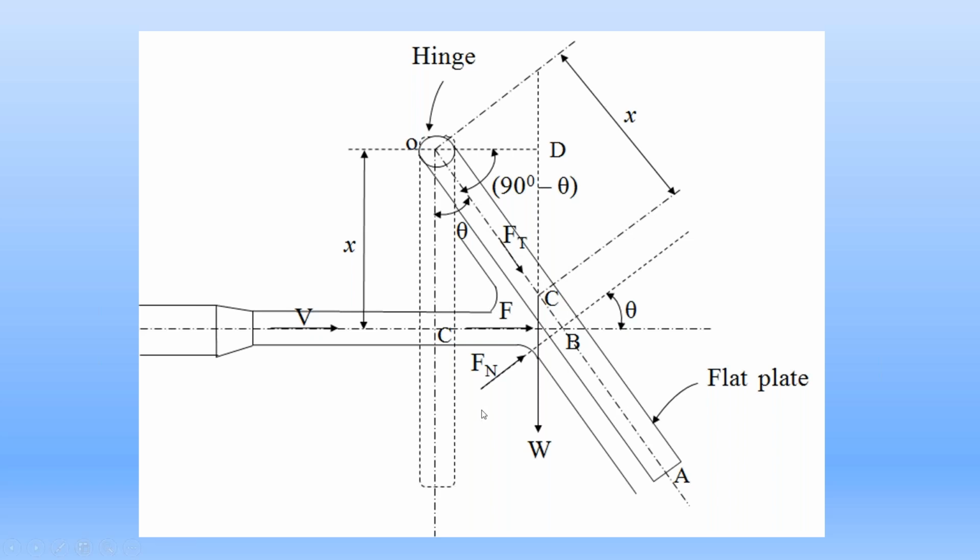We have this second force W, vertical. From the hinge point O to this force W, OD is the perpendicular distance. Just now we calculated this length OD, X sin theta.